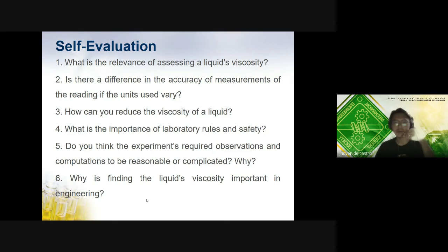viscosity is an important property of fluid. According to an article by Morse 2018, it is defined as the internal friction of a fluid or its ability to resist flow. This means that the viscosity of a product must be controlled and measured in production so that each batch is consistent from day to day. Knowing the viscosity of a certain liquid can help in determining the parameters required in order to process it. Hence, the machine type and the pipe to be used can be determined depending on the viscosity. Once the proper pipe is determined, the processing of the liquid will be more efficient.